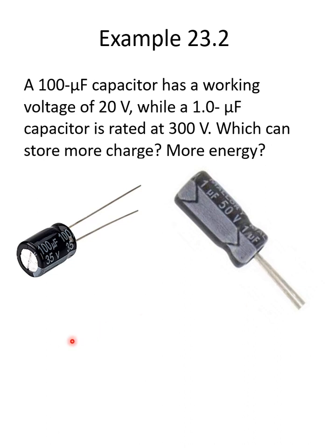And I just want you to look at these pictures. Here are two typical capacitors. I actually pulled these off, I think, the Amazon.com webpage. But you notice right here, it's written in small print, 100 microfarads. Now this one in particular, not matching the example, says 35 volts, meaning that's the working voltage. And this one on the right says 1 microfarad, and it has a working voltage of 50 volts.